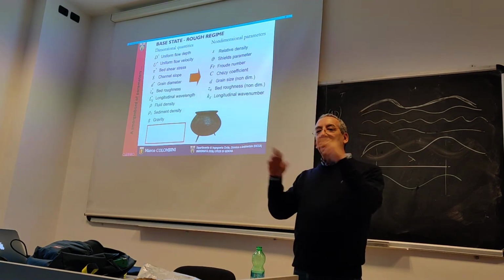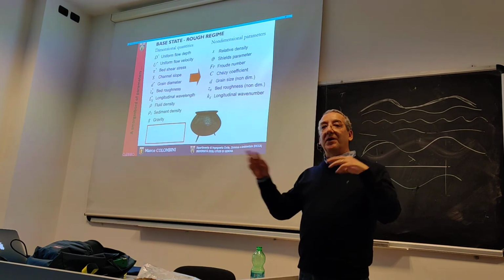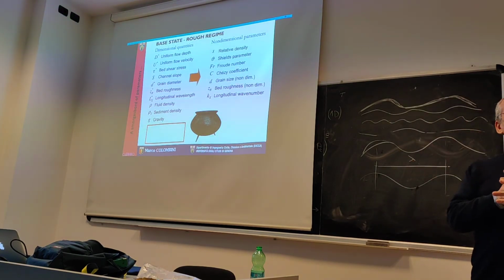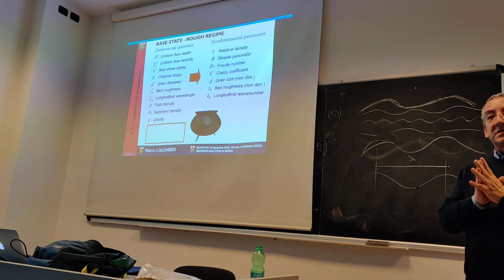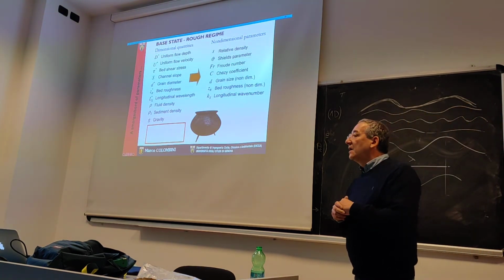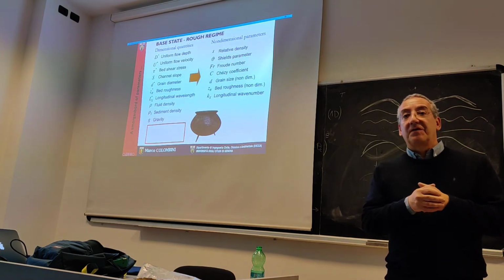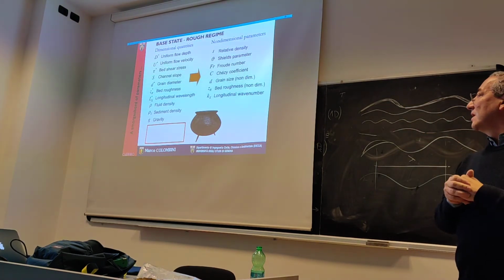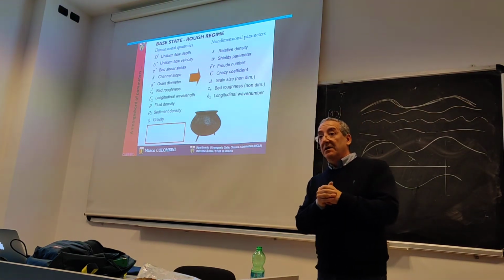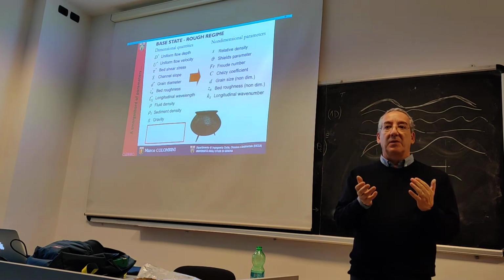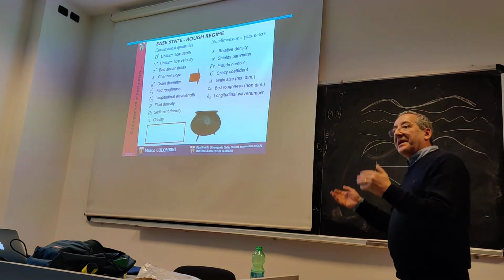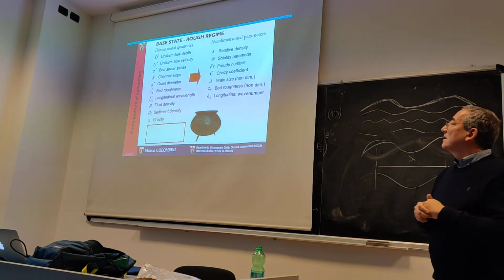If you have any relationship between quantities in a physical problem, and you introduce non-dimensional quantities, so quantities that are just numbers, that have no dimension, then the number of variables on which your functional relationship depends is reduced. It is very helpful when you are studying a problem in a lab, for example.